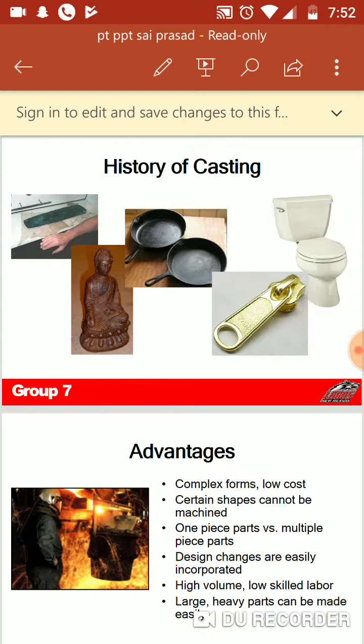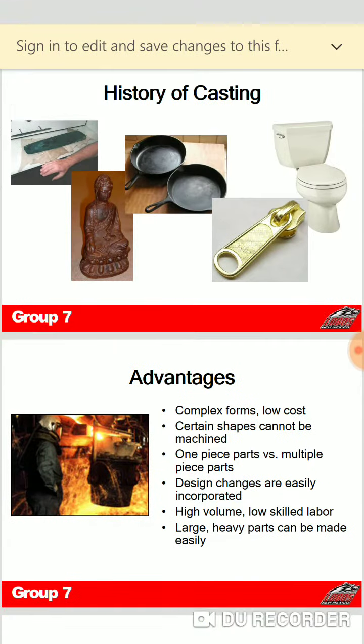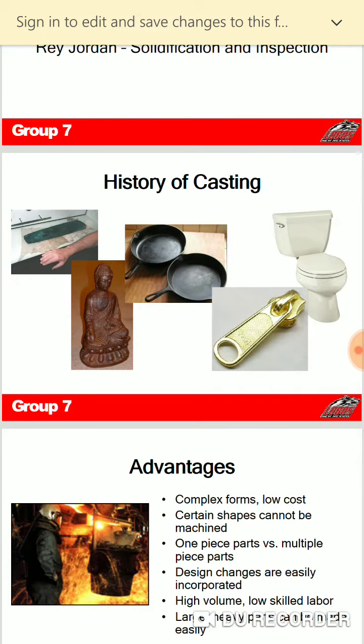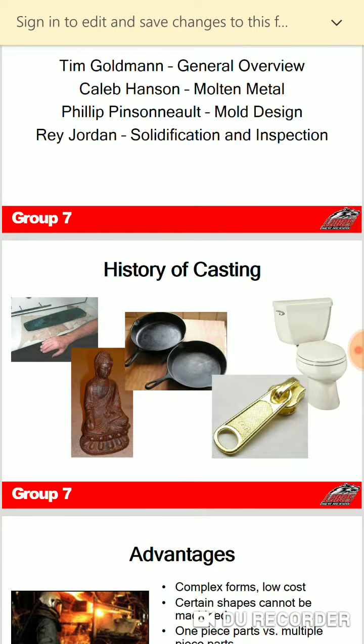Casting is a manufacturing process in which a liquid material is usually poured into a mold which contains a hollow cavity of desired shape and then allowed to solidify. The solidified part is also known as a casting, which is ejected or broken out of the mold to complete the process. Casting materials are usually metals or various cold setting materials that cure after mixing two or more components together. Examples are epoxy, concrete, plaster, and clay.